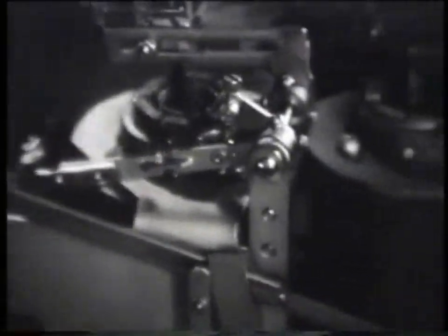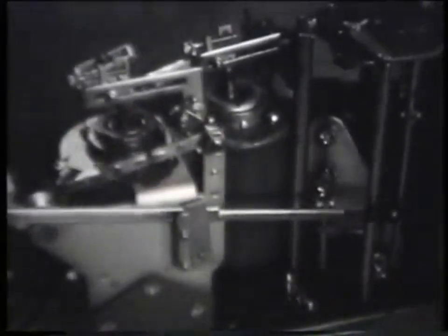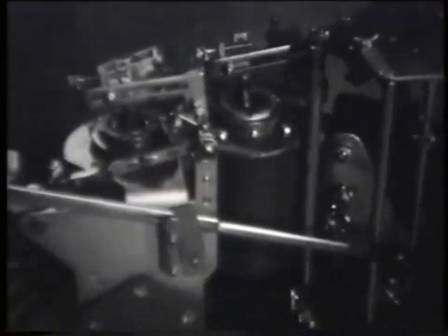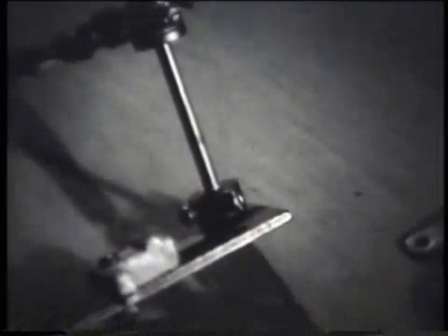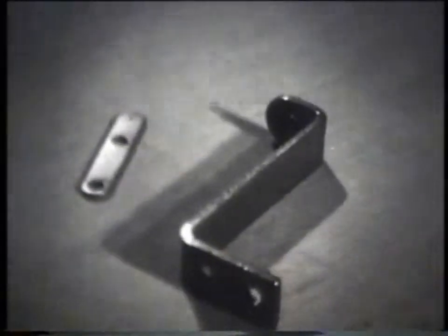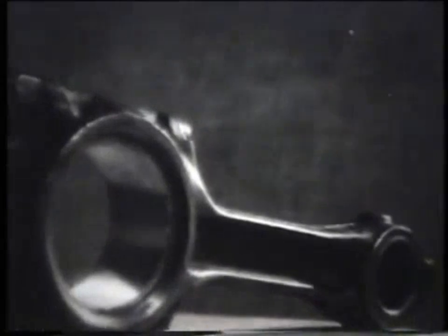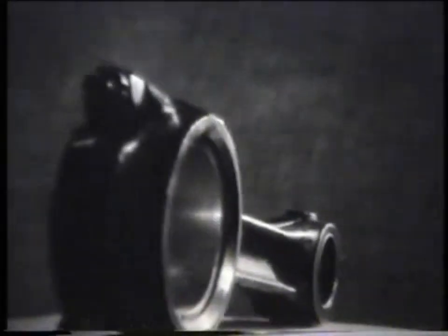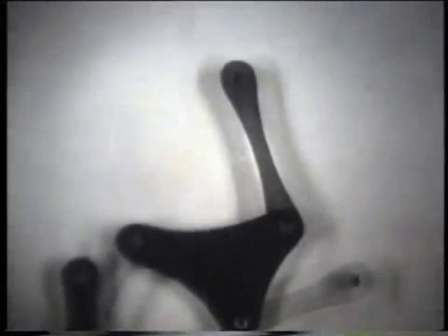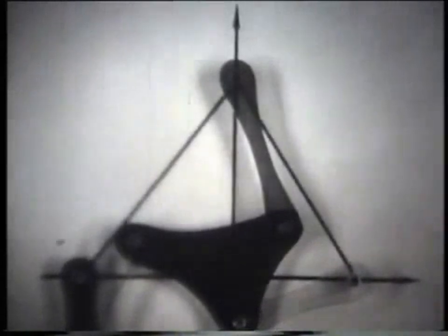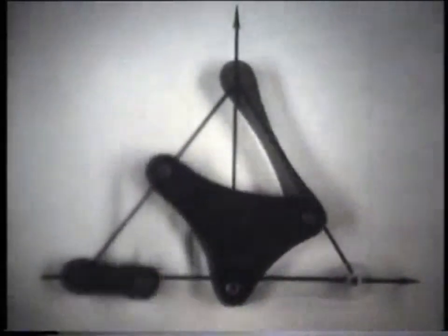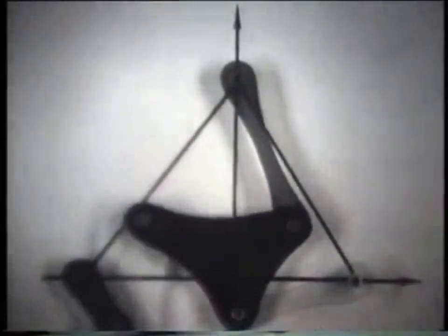The links of the mechanism are one or more rigidly connected solids that make up the mechanism. In lever mechanisms, one of the link sizes is usually significantly larger than the others. Often the links of lever mechanisms are made flat, having a constant thickness, but they can also have a complex shape. A fixed link in the accepted coordinate system is called a rack. Any link of the mechanism can be taken as a rack.